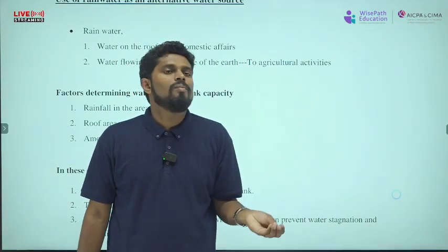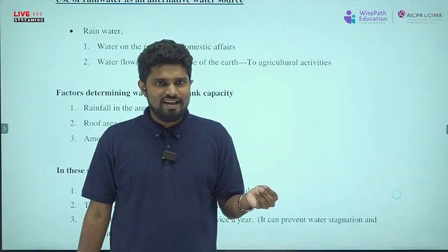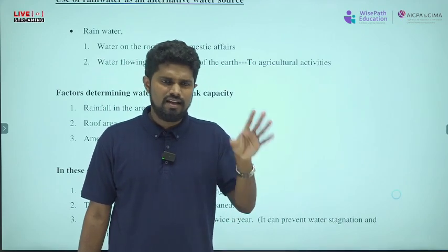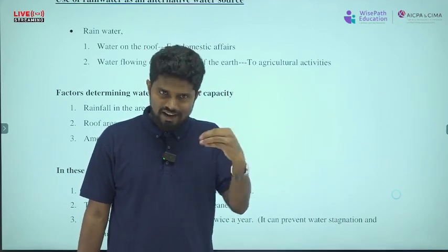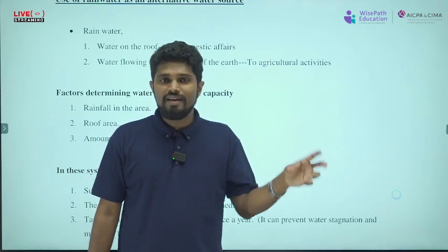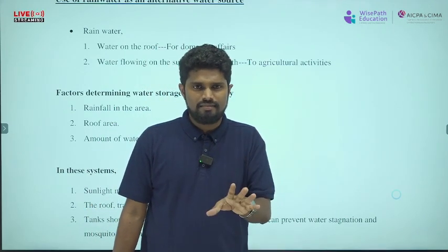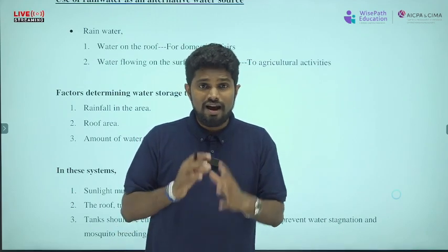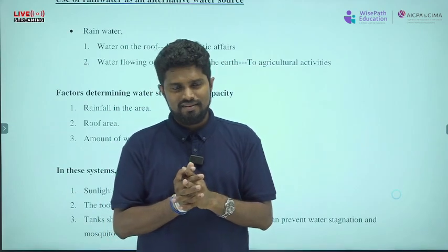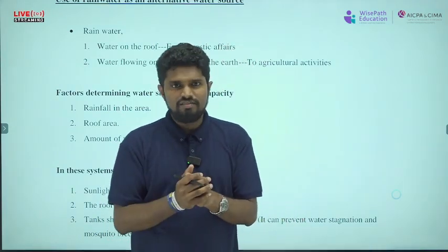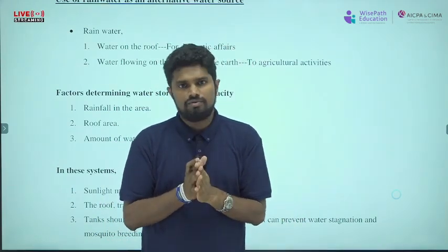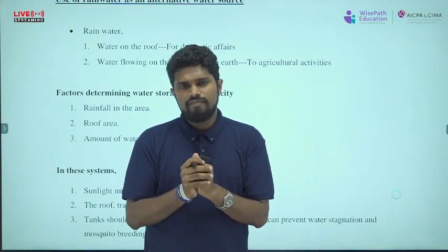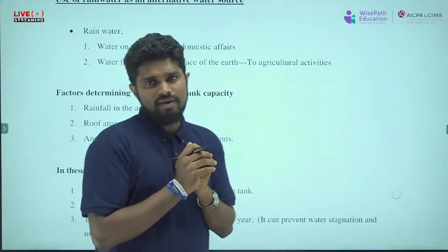And if we consider normally, a human consumes 100 liters per day. Normally drinking, washing, that's an average value. That value you can use for the calculation processes, guys. Normally, humans use 100 liters per day. For some calculation processes we use that value. You can use it, no problem, for your day-to-day activities.